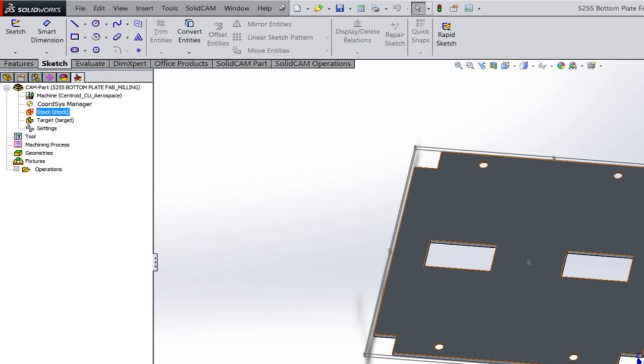Why? You won't be supporting these sides. These are going to flap. So you don't really care if these 2 sides are supported all that well, but we want them supported near where the end mill is. But you don't want to get too close either, because then the end mill or its tool holder might hit the clamps. Okay? So you need to be a little cognizant of that. All right, so we'll put a clamp here and here, and we'll machine these, and then we'll move the clamps and machine these final 2 sides.